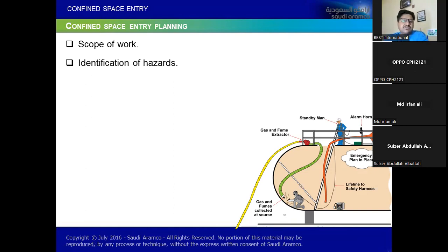And on the other side, the maximum duration is 2 shifts or 24 hours. Then after 24 hours, another permit is needed. The same permit can't be renewed again and again. That is the criteria, and it might be within your SOP or procedure for the PTW system. You can double check what exactly is written within your procedures, and compare those procedures with your client's.